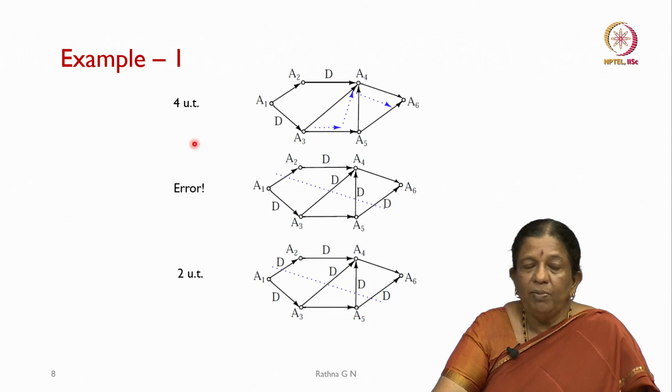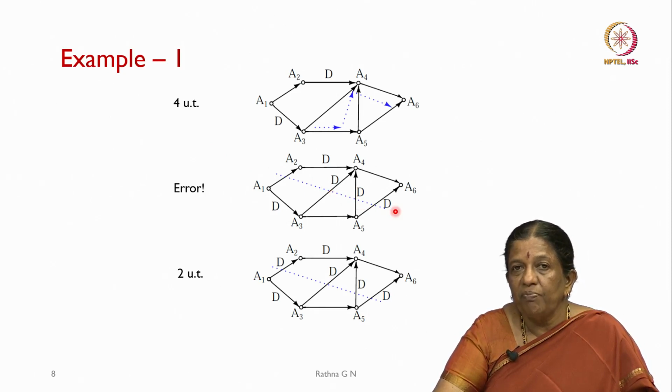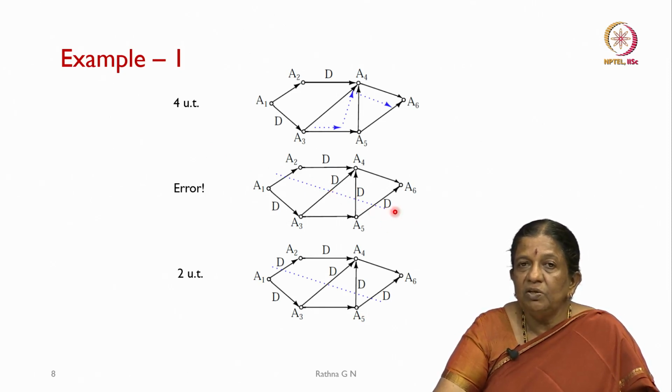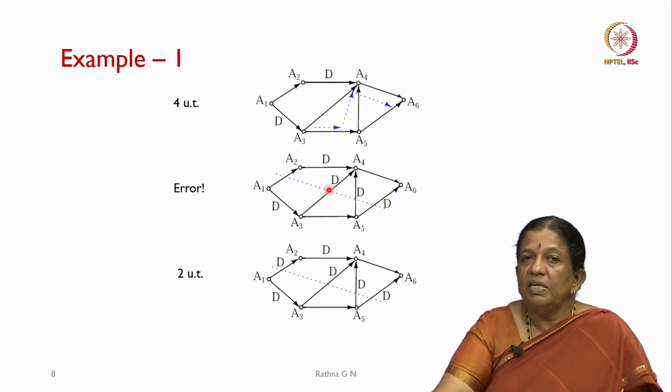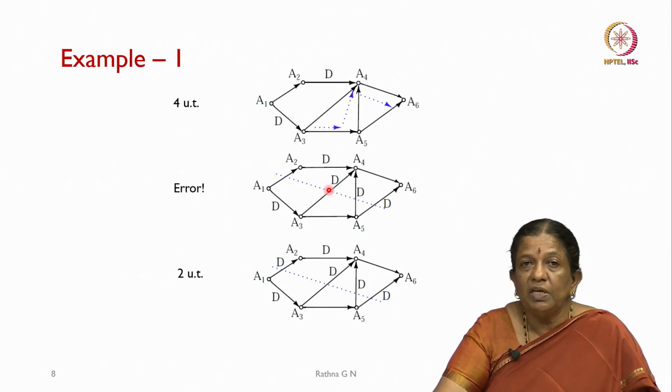We said that we will put in a cut set. So, I can cut the graph into 2 pieces in this way, and then we are going to introduce delay units wherever we have put the cut set, or a shift register, one of the things we will be using. As we can see, we have cut this into two parts this way, but we have forgotten to put a delay unit here, so this is an error. So, if we cut this properly and put all the delay units in the cut set, what happens to our critical path?